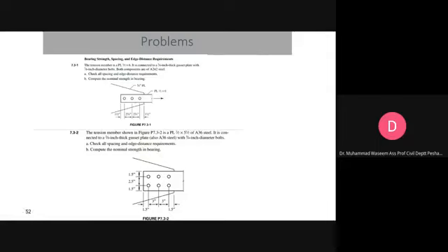I can give you some hints. Now, in this case, A36 steel is not used, okay? But we have A242. And you will be asking, okay, what is the Fu for A242? For A242, the ultimate strength of the material is 70 ksi, okay?